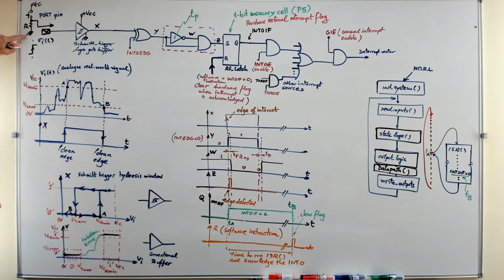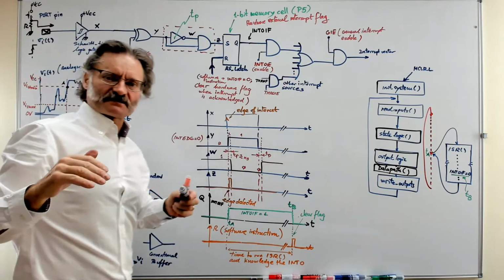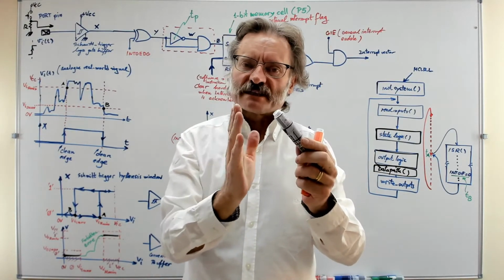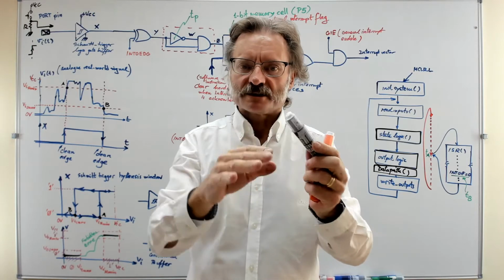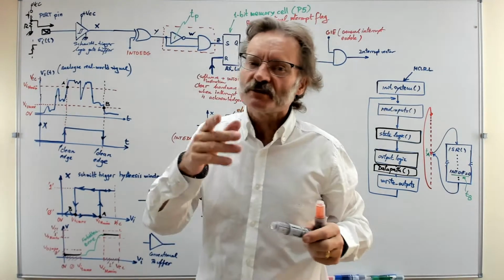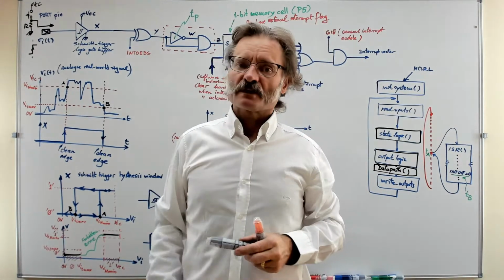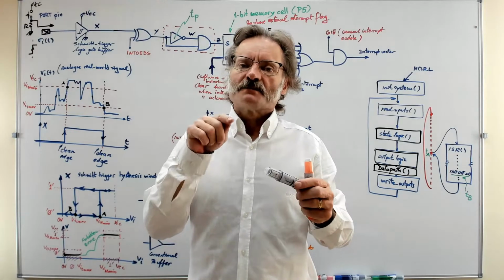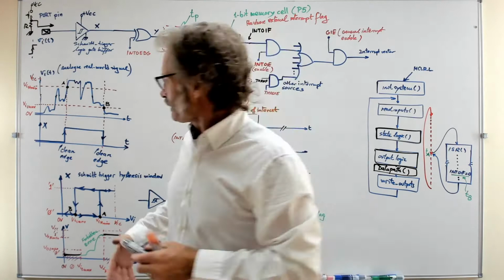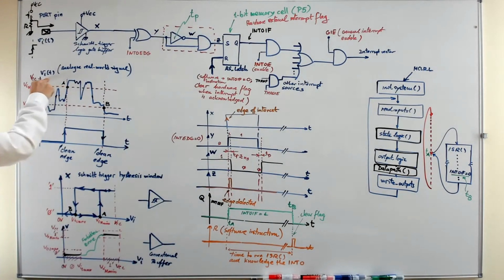Okay, so when you click, you generate this signal, but logically, because it's a button, it is the connection of a metallic part to some metallic contacts, and there is going to be bouncing, and who knows what the shape of the real signal is going to be. That depends on the pressure and on many factors. So indeed, the signal that you have as an input, even if you are imagining that clean edge, is not like that. It's going to look more like this.